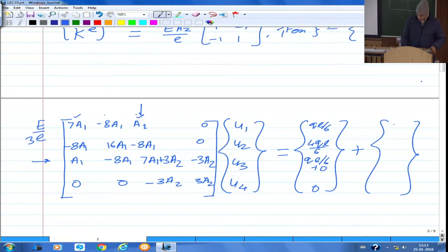Now if you look at the internal load vectors, we have at the first node here from the first element minus Q1 1, second is the intermediate node, so there is no internal load there, and then here we have from the third node of the first element, this is the contribution of internal forces to the global internal load vector. Then we bring in the second element. So for the second element is again here, say Q1 2, and then here we will have Q2 2. That is the internal load at first node of the second element, and this is the internal force at second node of the second element.